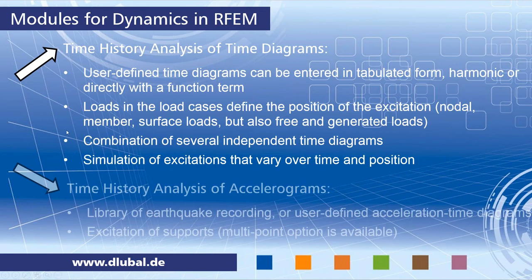The second we have available is a time history analysis of oscillograms. So you can either choose an earthquake recording from our library, or you can define the acceleration time diagram yourself, or import it from Excel. And here you have an excitation of supports. So this is not a free excitation somewhere in the structure. It is an excitation of supports, but we have the multi-point option available. So this is similar to the response spectrum analysis.